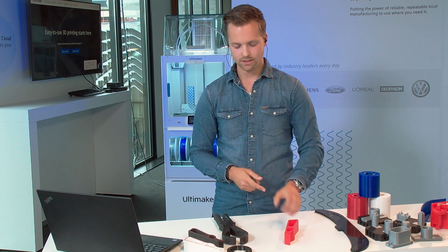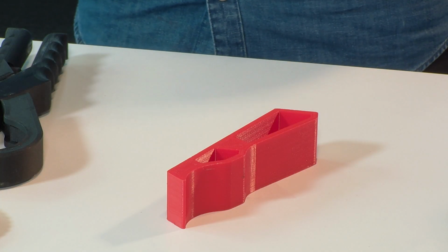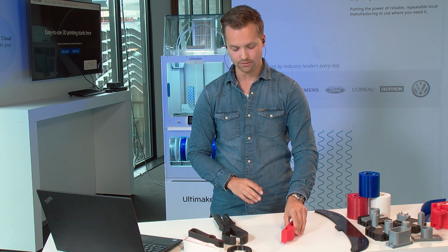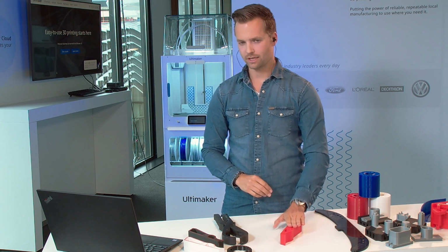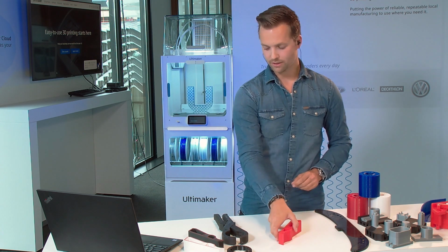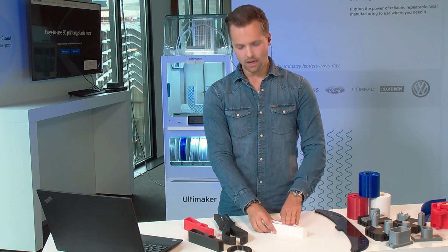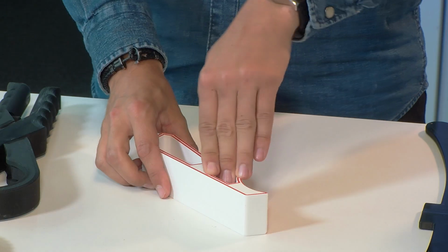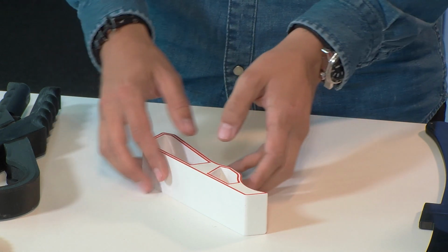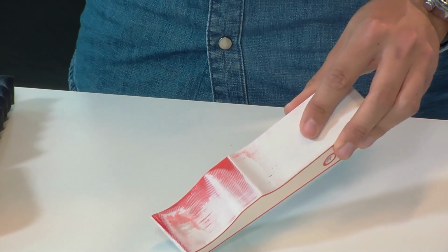What we did here is make the height higher, so you have more contact surface area to push these cans, and it's more lightweight as well than the metal part. And also a nice feature, we took this a step further. With Ultimaker Cura, we changed the outer wall extruder. So the inside we print with a different color, and the outer wall we also print with a different color. When you run this through the line, when it starts to wear down, you will see that the outer layer is wearing off.